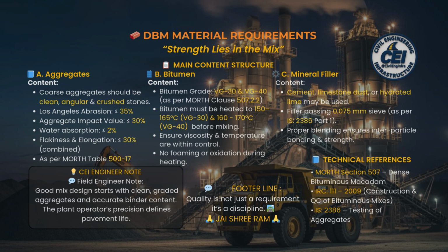C. Mineral filler. Fine but essential, ensures interparticle bonding. Cement, limestone dust, or hydrated lime may be used. The filler must pass through 0.075 mm sieve, as per IS 2386 Part 1. Technical references. MoRTH Section 507. IRC 111, 2009. IS 2386, Testing of Aggregates. Quality is not an act, it's a habit that defines the road's life.